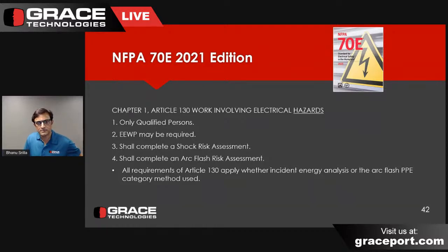And you determine additional protective measures. And if you're using the latest editions of Z462 and 70E, you've got to talk the language, right? You've got to train your workers and make sure the training's compliant and that you change the language, because the wording and terminology has changed. That's another thing that's changed with these standards. So additional protective measures are the outcome of a work task shock risk assessment and arc flash risk assessment.